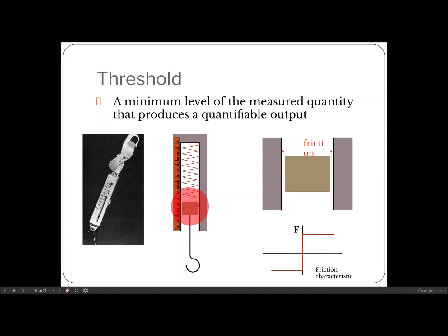But sometimes if you don't have a really good weighing scale, there is friction in here, non-negligible friction. So when the suitcase is not that heavy, the friction in here will prevent this spring from expanding, until you attach considerably enough weight to overcome the friction of the weighing scale.